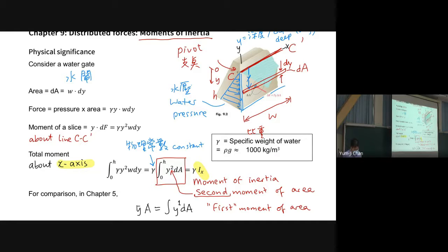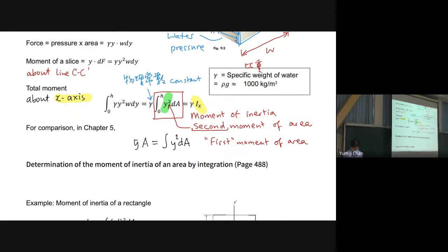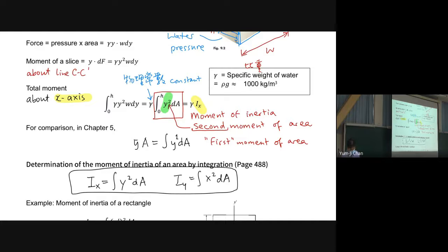But in the integral, we have y squared here. So in mechanics, or in mechanical engineering, Ix is equal to the integral of y squared dA and Iy is equal to the integral of x squared dA. If I ask you to determine Ix, remember that it is y inside. If I ask you to determine Iy, then it's x inside.